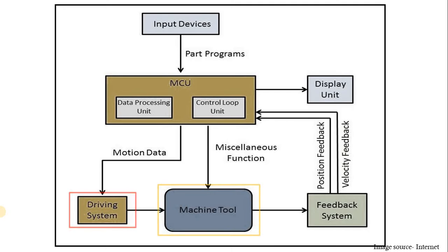So the driving system and machine tool are operated by this MCU. The MCU gives signal pulses to execute different types of motions by the respective motors. These motors are expected to lose their desired accuracy and precision through resistive forces at the cutting tool, backlash at the kinematic pairs, and inertia of the moving elements during acceleration and retardation.